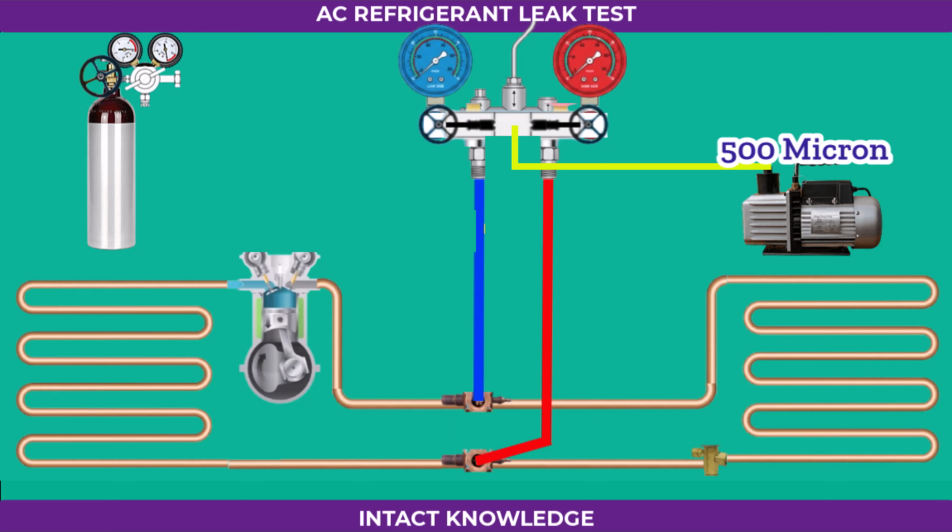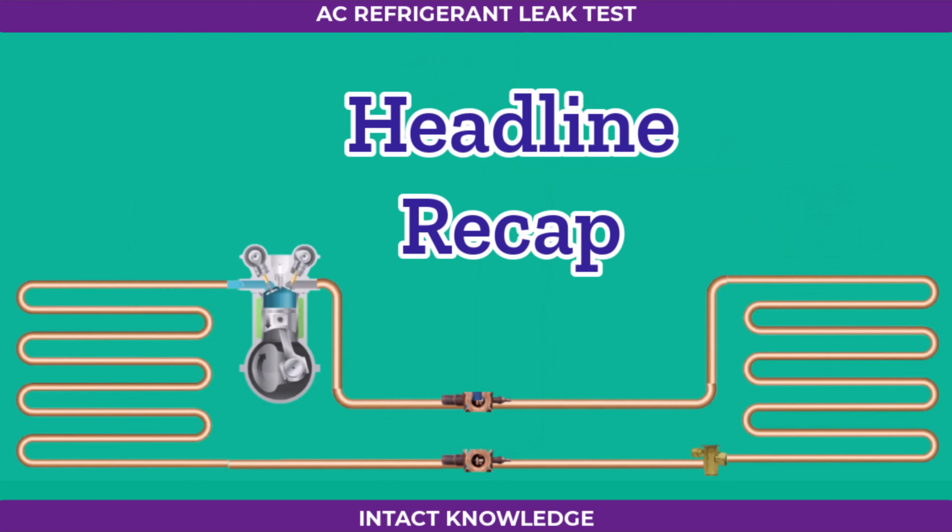That's the complete professional procedure for leak testing with nitrogen gas. Safely recover refrigerant, use the proper test pressure, pressurize gradually, check with soap and detectors, purge during brazing, and vacuum the system thoroughly afterward. Following these steps ensures accurate testing, prevents system damage, and maintains long-term efficiency and reliability.